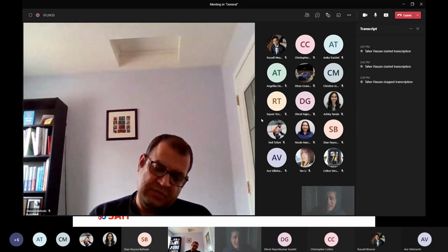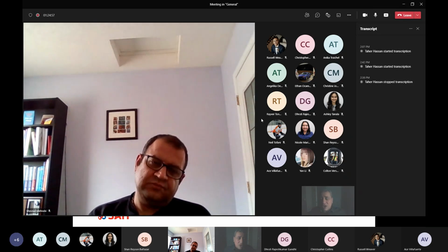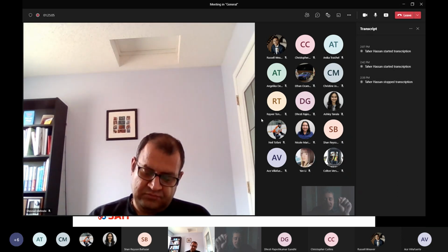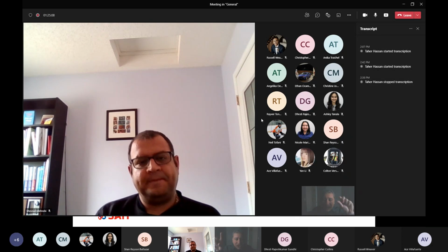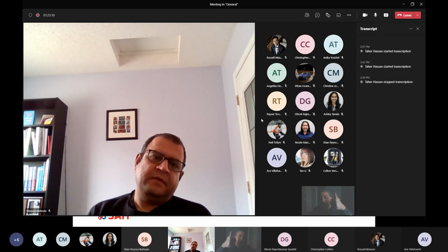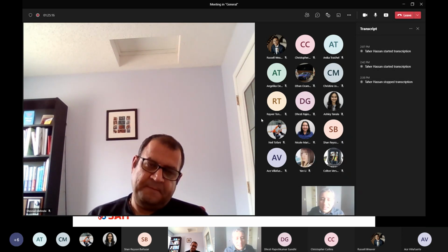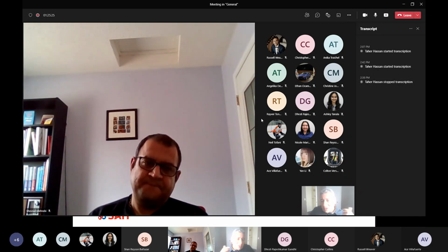However, what you see on my screen is the theoretical curve, and the machine will give us 2 values, and that's something you will see in the data. 2 values written in numbers, not as a curve, just numbers written. One is the ultimate force, and number 2 is the breaking force. And then you should be able to find the ultimate stress and the breaking stress. Can anybody tell me how? So I gave you a force, and you want to find the stress.